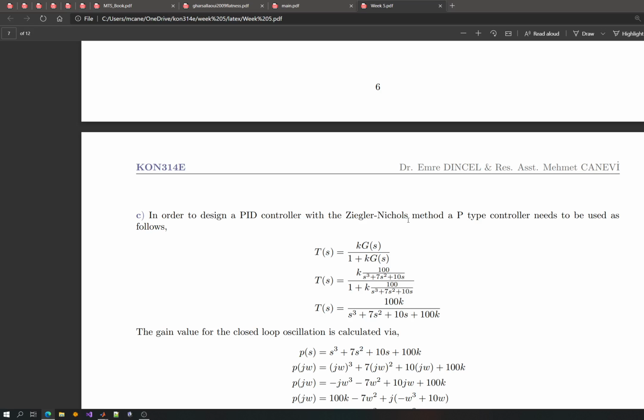You're just plugging in the values into formulas that are derived from Ziegler and Nichols, and they have some theoretical background on why they can provide you with general formulas just by using the stability margin. They're just giving you a standard PID controller that has a distinct and very well-known step response.